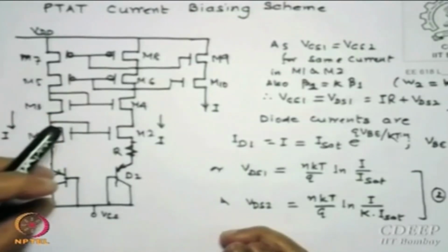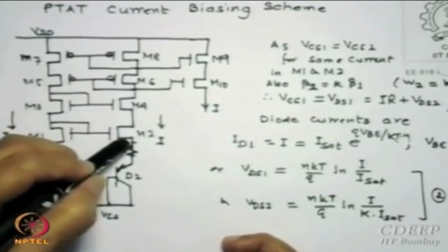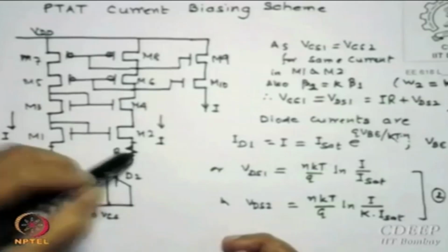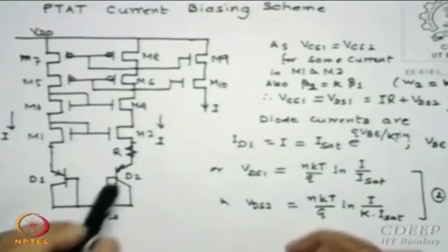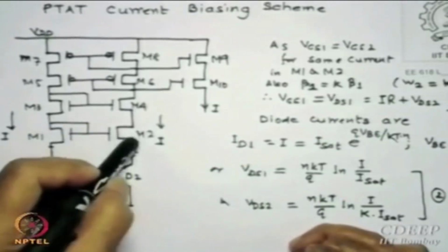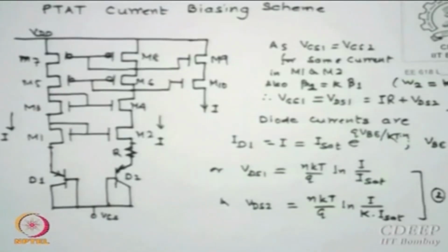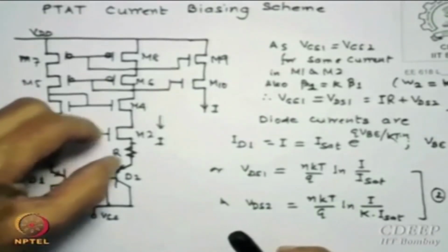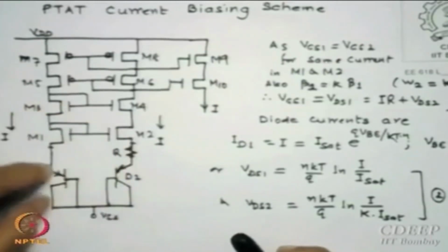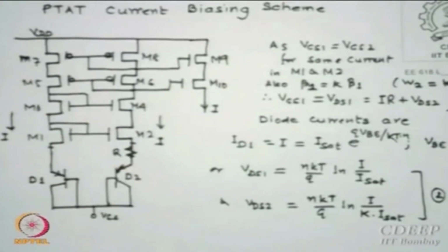This voltage plus the drop here must be equal to this voltage plus this drop plus this voltage. But these diodes are taken identical, so for practical purposes this must be equal to this plus this. Is that clear? I wrote it, but it obviously was not clear, so I repeat: this potential equals this potential plus this, because the drop here and the drop here are the same. The reference is a little higher, that is the only difference, but in subtraction they are equal.